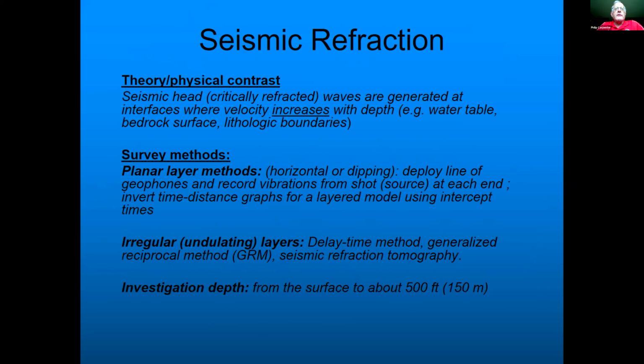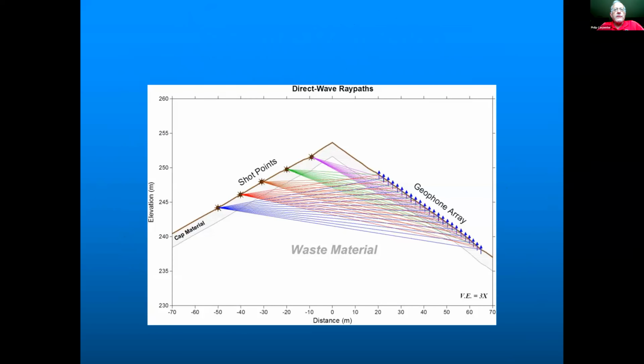I'll skip over that. Some more background. Again, the order on this needs to be fixed. Okay, so here are our shot points. This was on the west side, and our geophone array was on the east side. Here's your cap material, your cover material, and your waste is inside here. So your shot points would fan out like this.